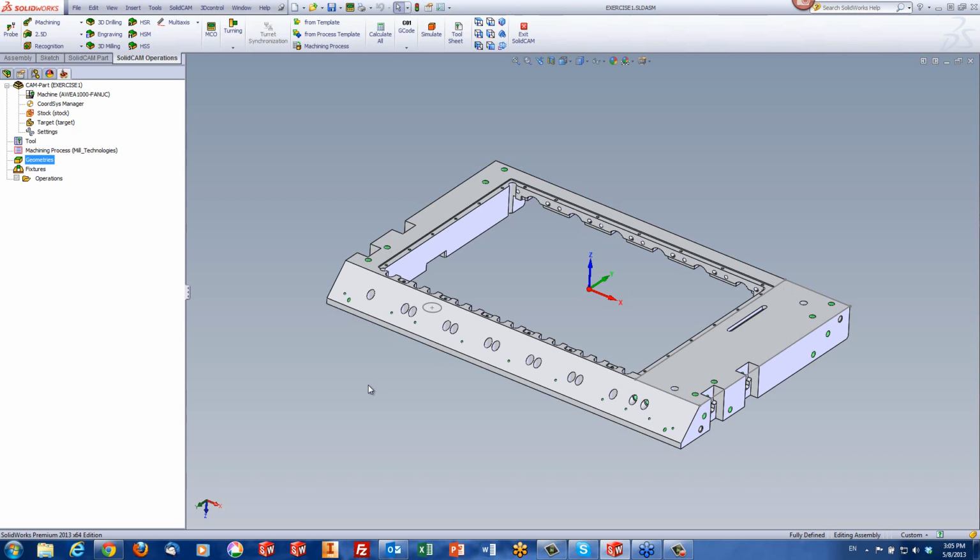Also, it should be noted that it doesn't see anything on the side. It only sees the exact surface that you pick, and that's the surface it will work on. So if you have a surface on the side that may interfere with your machining, it won't see that surface. It may even gouge that surface. For that, we also have a tool called gouging, which we'll also take a look at as we go through HSS.